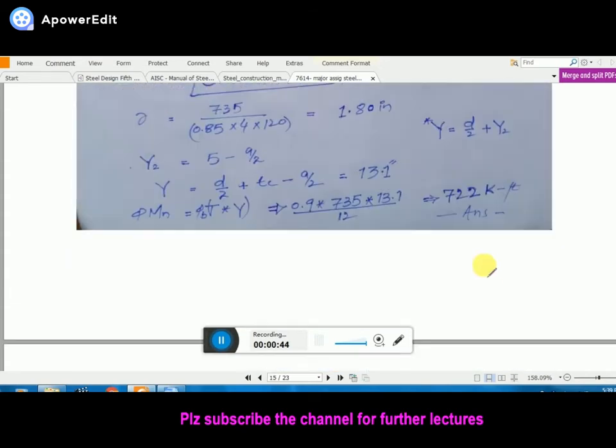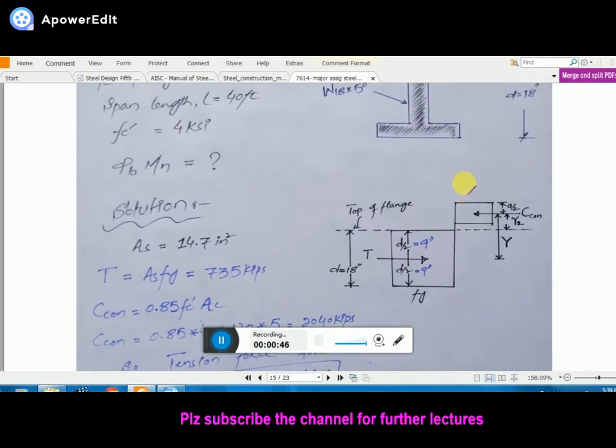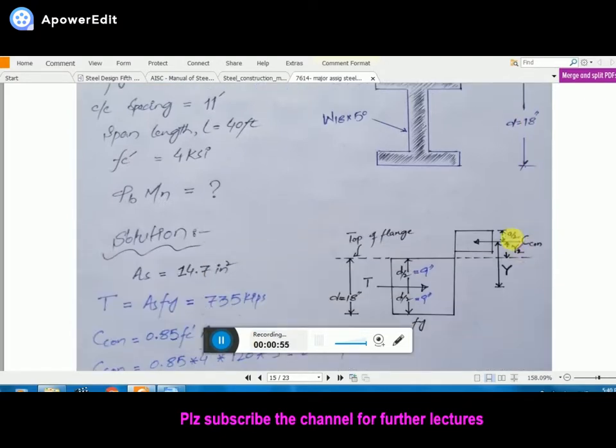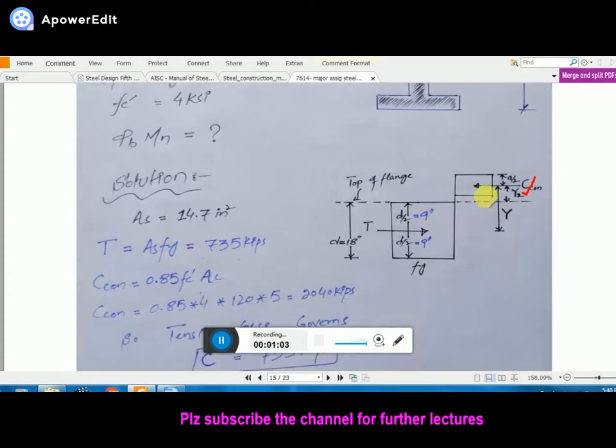One thing I want to show you is that in question number 5, it is very important to note down what y2 is, because it will help us in the upcoming part of question number 6, which is remaining. y2 is the distance from the top flange of the web to the center of the compression force, or the compression of the concrete block.